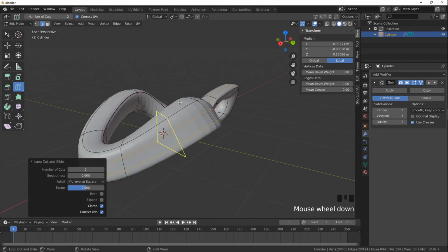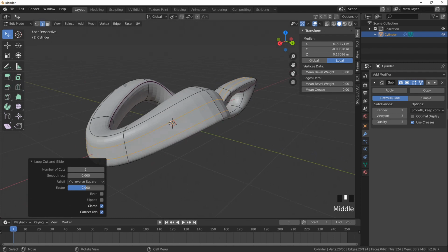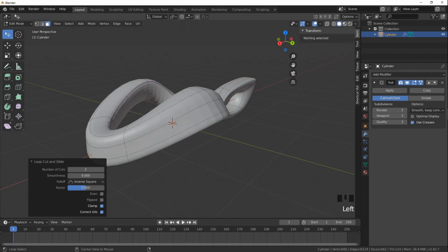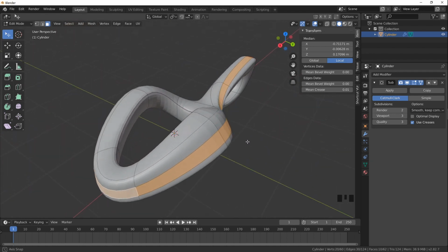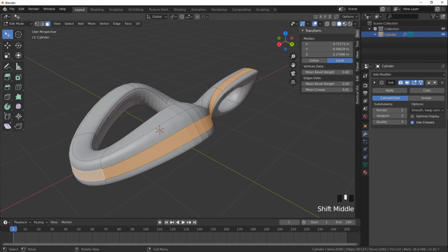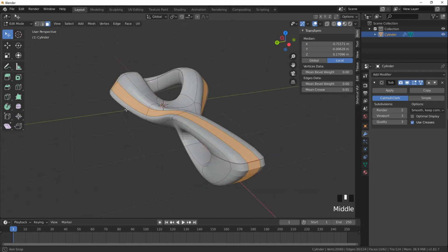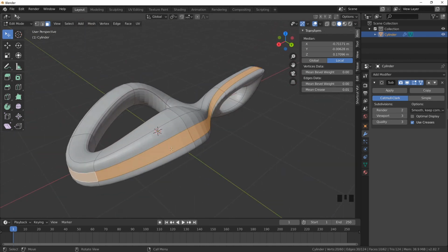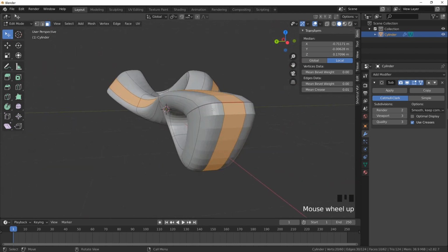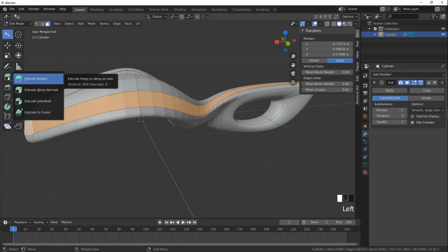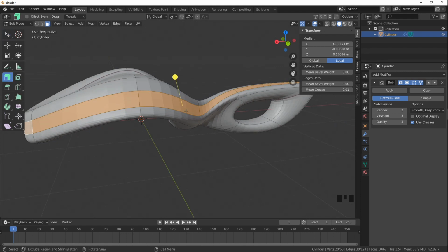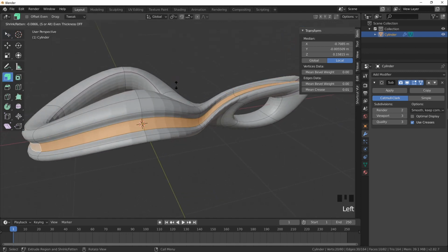Remember to return to the selection tool, typing W, and now selecting the faces, we can, for example, select this new loop that is inside. We can now, for example, make an extrusion along this entire loop that goes a little bit inside the geometry. So in the Extrude tool, if you hold the left button of the mouse, you can use Extrude along normals. And from here, you can do the extrusion and make this kind of channel along the geometry.